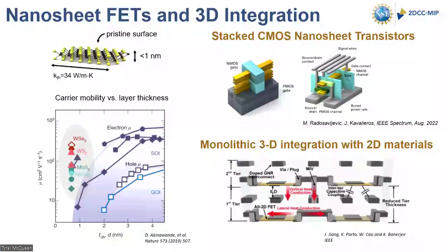And furthermore, it's got passivated surfaces, right? Because it has these van der Waals surfaces. So you don't have dangling bonds like you have on silicon, which is where all the work in developing an oxide and having a really good quality interface comes in, right? You don't have to worry quite as much about dangling bonds, but the interface is still important, I should say.